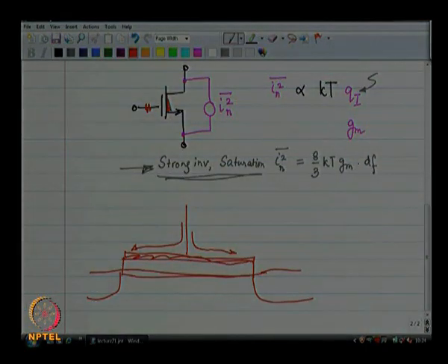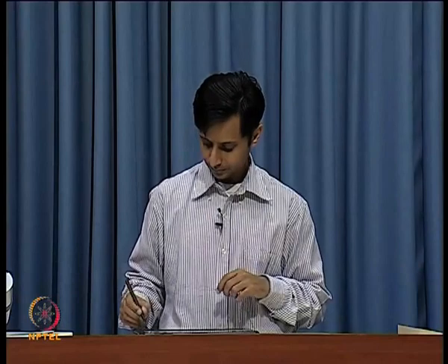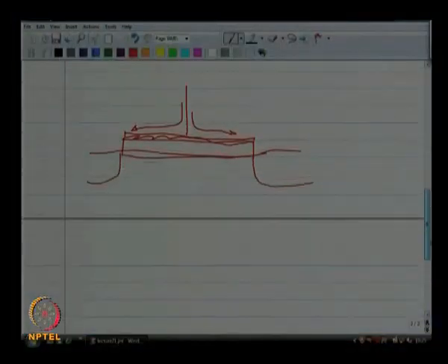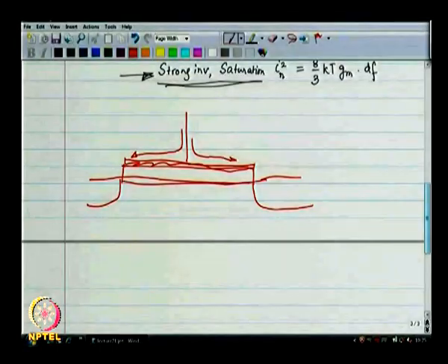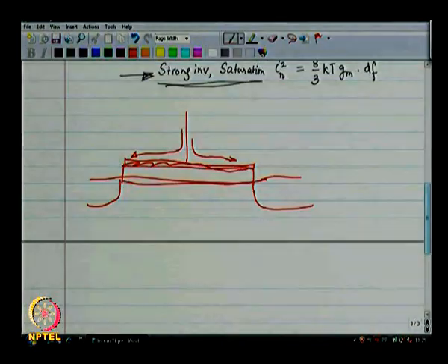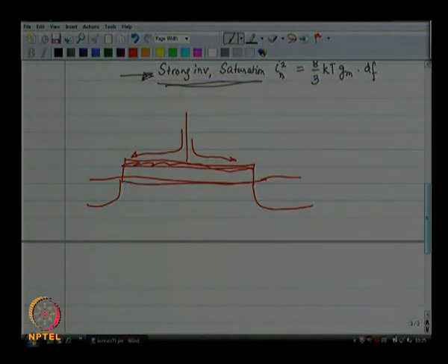And the gate is not made up of metal, it is made up of polysilicon. In all modern processes, the gate is no longer metal. Polysilicon is also the same material that is used to make resistors. So the gate material is resistive, and as a result you get an effective resistance as far as the gate is concerned. Whenever you have a resistance, you can think of electrons jiggling around because of temperature, and that is going to cause a voltage.